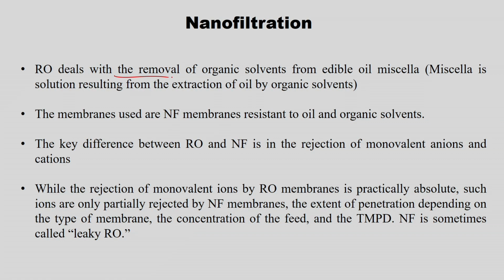So, the RO deals with the removal of organic solvent from edible oil micella. The micella is nothing but a solution resulting from the extraction of oil by organic solvent. It is used in the extraction of oil, right. So, extraction of oil is done using the organic solvents. Whatever the solution you get, that is nothing but a micella. So, the RO deals with the removal of organic solvents. The micella contains the organic solvents as well as whatever the component to be removed from the oil. So, to remove the organic solvents from the edible oil micella, the RO is being used.